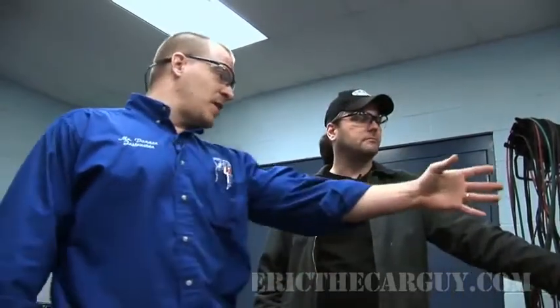It's funny, back in the day when we did tailpipe emissions in Pennsylvania, for this car, if this was a tailpipe test, I think the HC limit was less than 220 and CO around 1.2, but they jacked it up, I think in 94, 95, to under 130 for HCs and less than 0.8 for CO. So it would technically pass. Right now, this car would technically pass, but with a check engine light and a misfire event it will not pass? That changes now with OBD2, but if this was a tailpipe emission test, this car would pass emissions right now, interestingly enough, with a dead misfire.